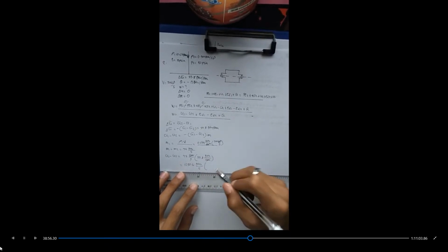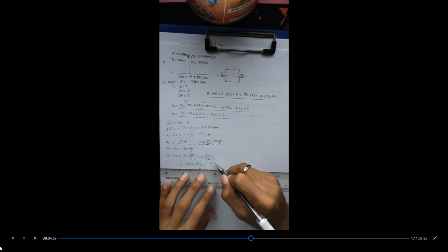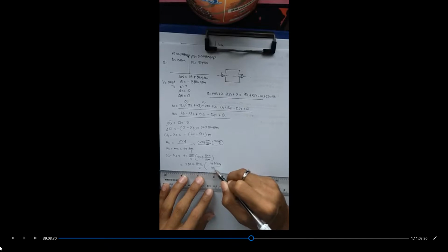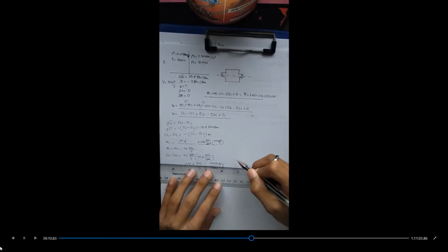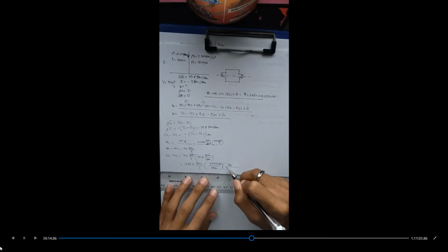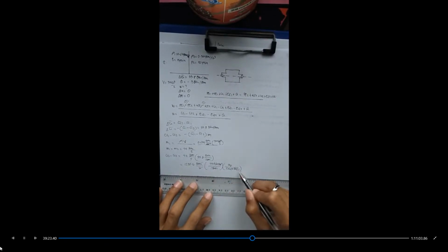Since we are solving our work in horsepower, I'm converting BTU into foot-pound force. So 778 foot-pound force per 1 BTU. Then converting foot-pound force into horsepower, 1 horsepower is 550 foot-pound force per second. Just like that, cancel BTU, cancel foot-pound force per second, and we are left with HP.